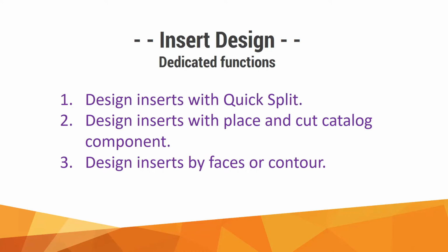We're going to look at three different methods for designing inserts for tooling. Doing this requires trying out several functions that you'll find in the dedicated Inserts menu in the Mold Design toolbar. Hopefully this will illustrate the pros and cons of each method and help you make better, faster mold designs.